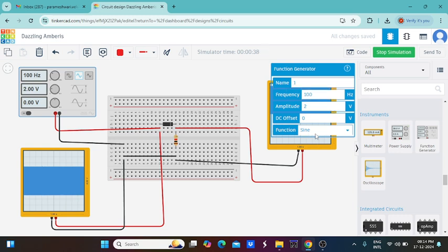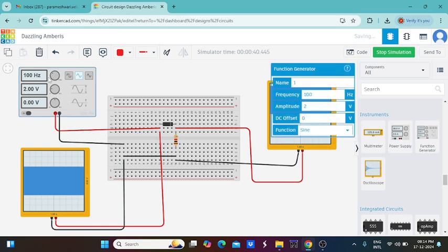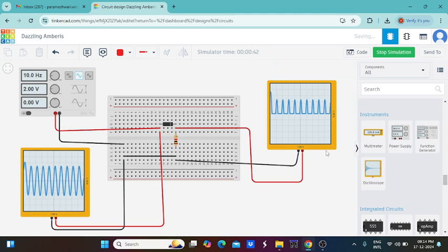Here I can take the sine function. So the sine function can be enabled here. Because of choosing a low frequency, the signal can now be easily seen. If you increase the frequency, automatically the time period becomes very small, because time and frequency are inversely proportional to each other. At that time we can't see it clearly. Because of this reason, I have chosen the frequency as a very low value.